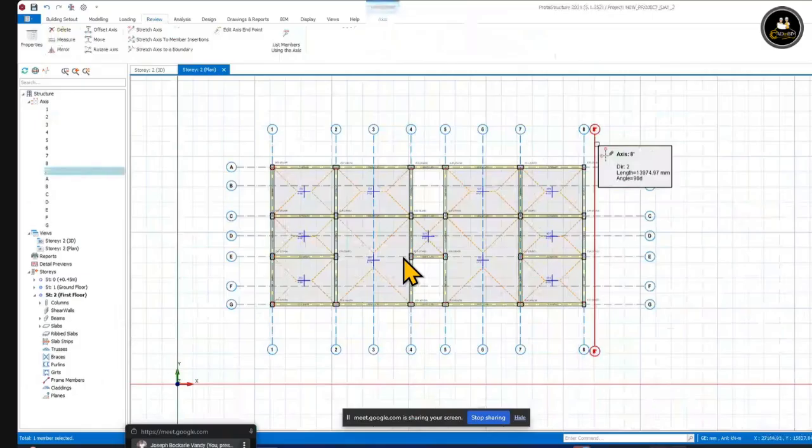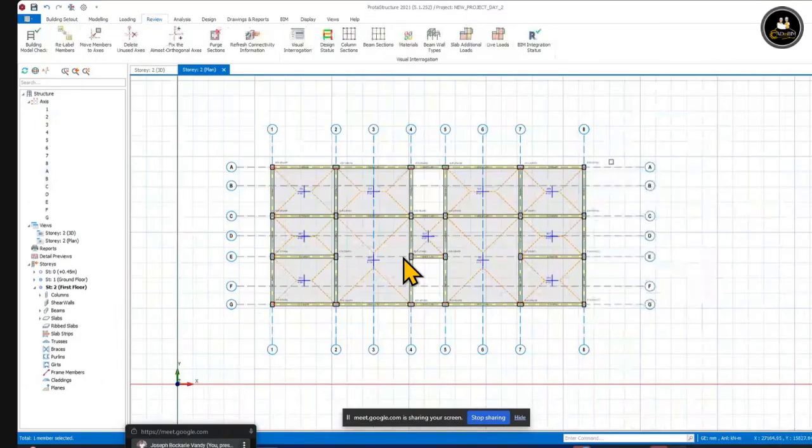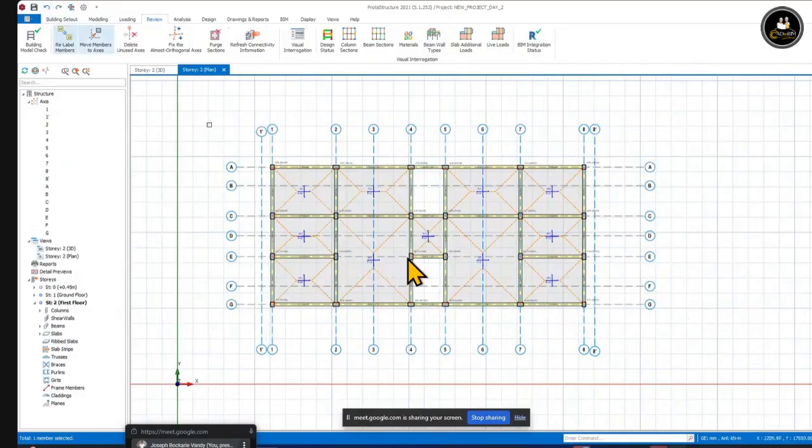At times we will have so many axes and you might not know which axis actually is not in use. When you have a very complicated model, you have drawn so many axes, not vertical, some are curved, some with other angles. So you can actually ensure that you eliminate the unused ones. Just go delete, you see how it will work.